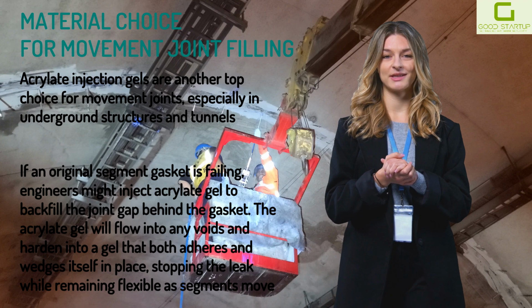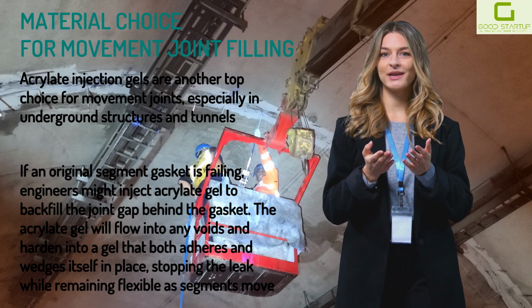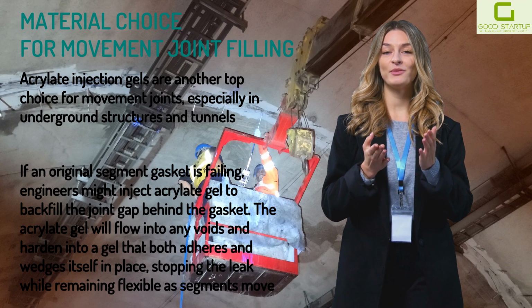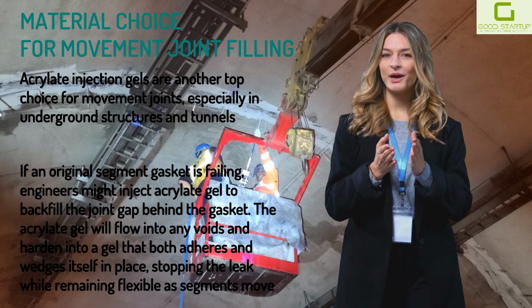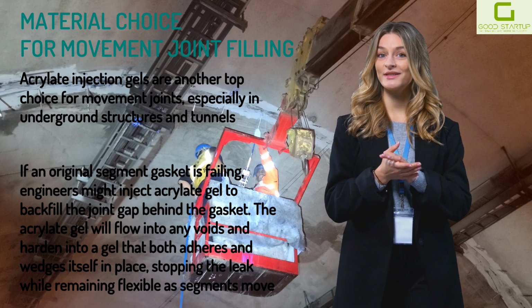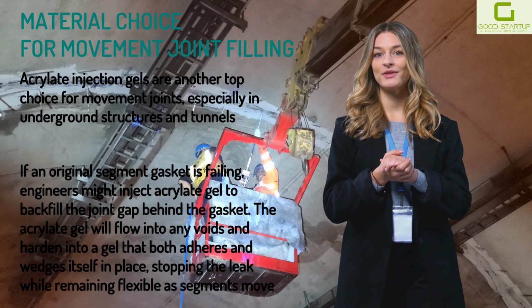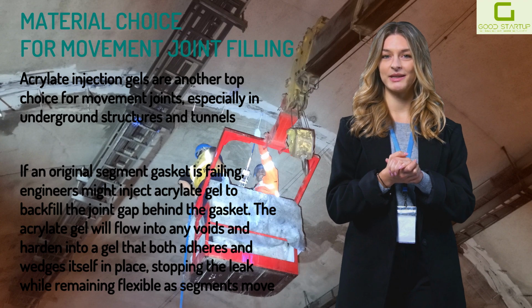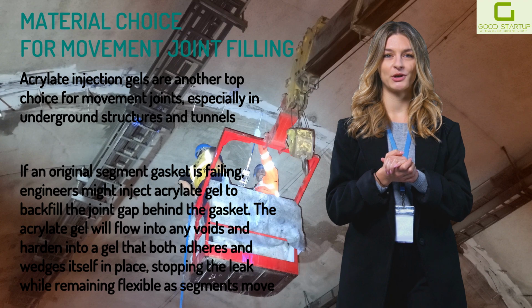If the joint dries, some acrylate gels can shrink slightly, but upon re-wetting they swell back. This reversible swelling ensures a long-term seal even with wet-dry cycles. Because of these traits, acrylate gels are often used for post-construction joint sealing in tunnels. They can form an elastic waterproof membrane within the joint or even a curtain just behind a joint if injected beyond the lining to block water ingress.